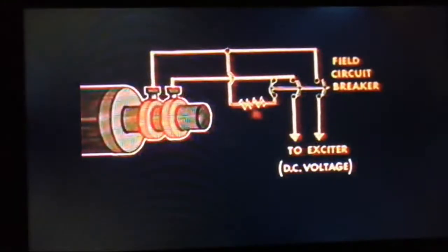Suppose, just as the main breaker contacts are about to part, another set of contacts closes to add resistance in parallel with the main generator field circuit. When the DC contacts open, field currents still flow through the resistor. This flowing current in the charged field coil permits magnetism to decay slowly, and very high voltages are not created.